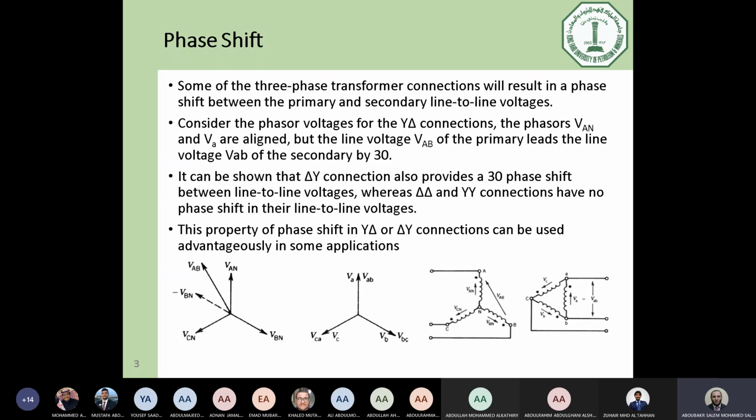We agreed from the last class that a three-phase transformer can be constructed in two different ways, either connecting three single-phase transformers together or creating a complete core for the three phases. And if we use three single phases, when we connect this transformer as a star or delta connection for both primary or secondary, we have to consider the flux direction and dot coil rule when connecting the three phases together in order to establish the flux in the right way.